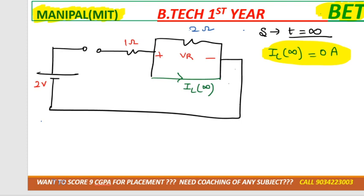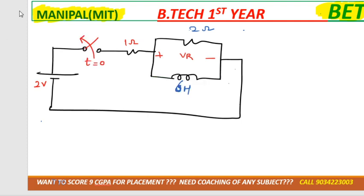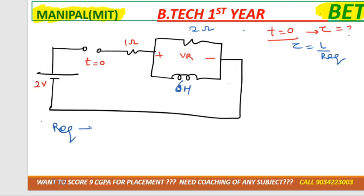Yes. So step number 3, we need to draw circuit at t equal to 0, and we need to calculate tau. Tau is how much? That is L divided by R equivalent. So at t equal to 0, the switch is opened, right? For calculation of R equivalent, voltage source must be short circuit.